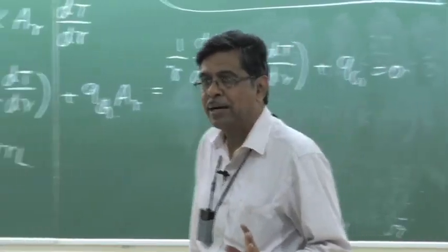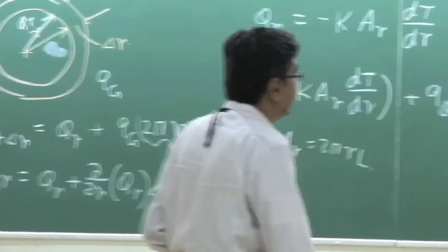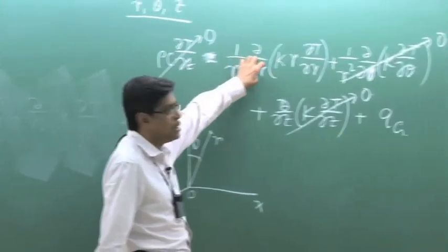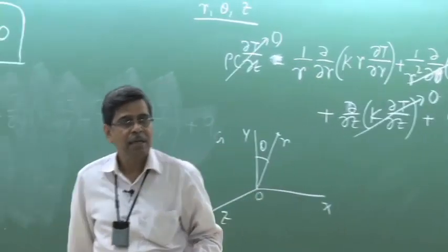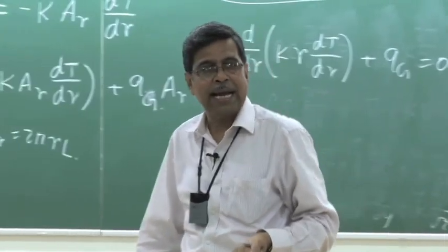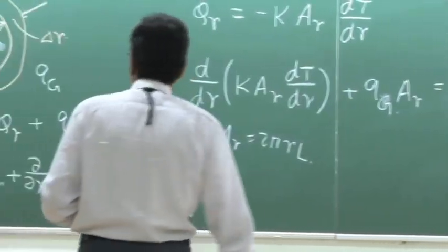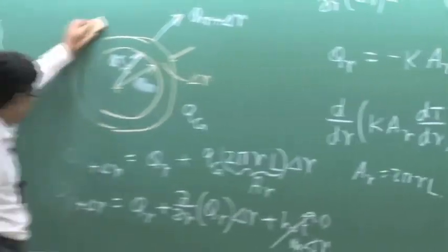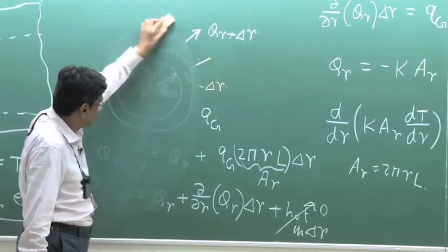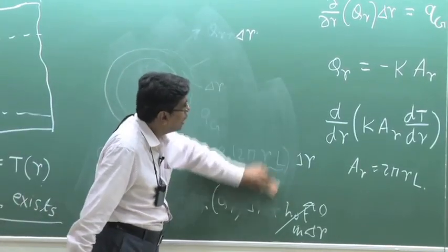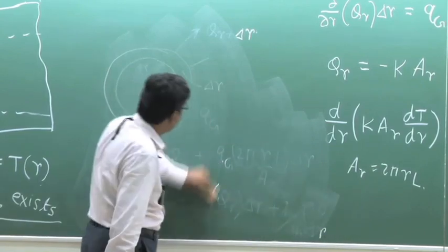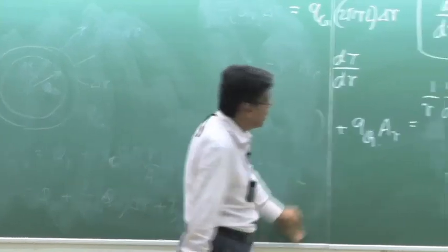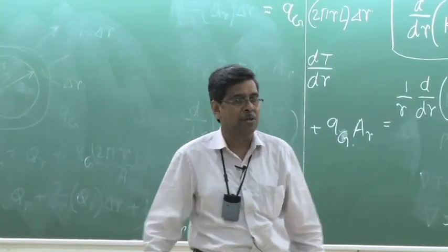You can see that this is not being done in the class, but the easiest way is to convert this into cylindrical polar coordinate system by expanding this divergence k grad T in the respective cylindrical coordinate. Now, after this, my job becomes much simpler, school-level mathematics, to integrate this equation. And before that, I consider another simple case, that k is constant. We consider that k is constant.